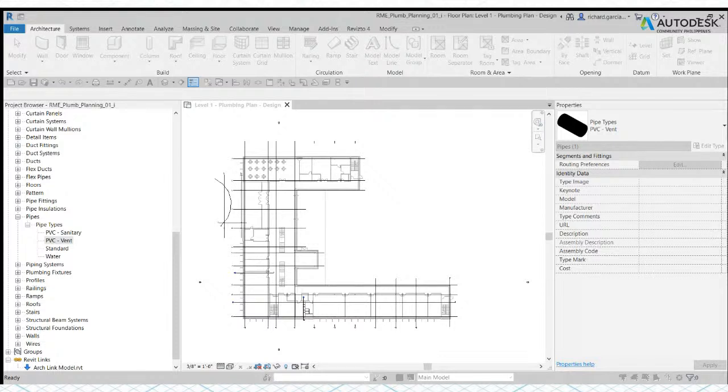And then if you want to add a new size for that, then there you go. So there's now the new size option for that. Okay, so let's say, for example, let's create 1/2. Do we have 1/2 here? So we don't have. So I'll select new size for the plastic schedule 40. So I click that one. So I'll put here 1/2 inch.